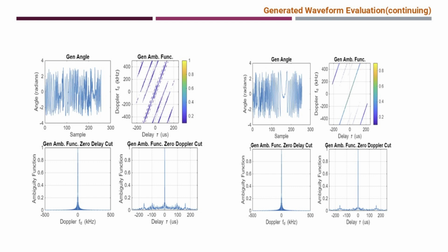The network generates waveforms with a similar ambiguity function shape as the training data. Multiple parallel ridges are observed with a tilt in the ambiguity function due to range Doppler coupling. The side lobe levels are also better in comparison to a thumbtack ambiguity function of random noise, where it is near zero level. The waveforms with a thumbtack ambiguity function are Doppler sensitive, but the generated waveforms are Doppler tolerant due to the tilt in the ambiguity function.